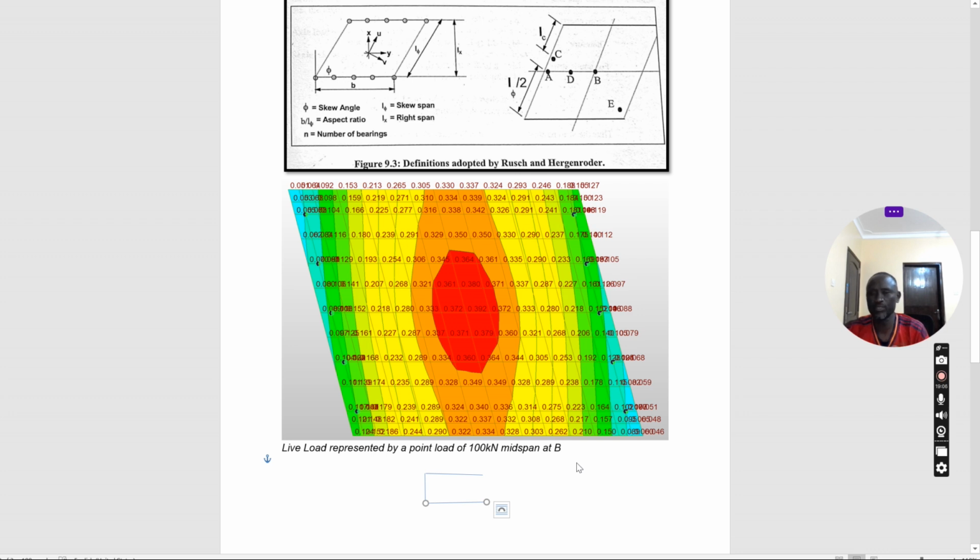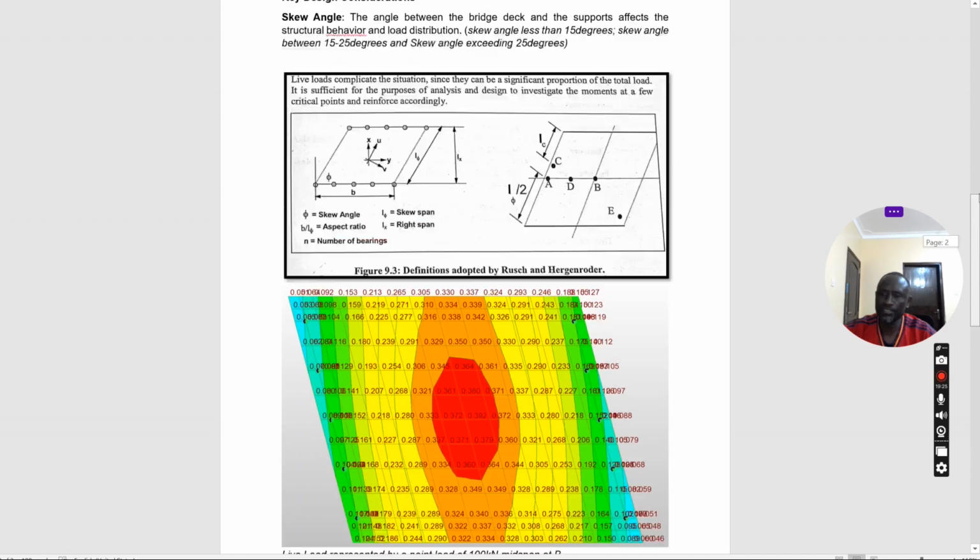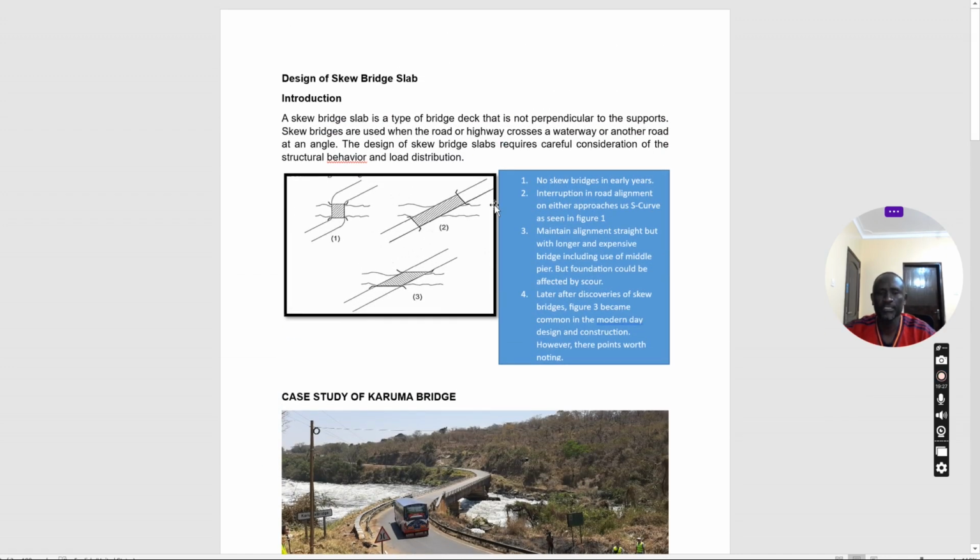it takes on that twisting effect, because, as I told you, we have seen the imbalances. This area tends to take more loading, but this load tends to reduce in this direction. It means there's twisting of this deck system throughout. There's moment throughout. There is shear value. So you need to take care of all this. So this is briefly about skew bridges.